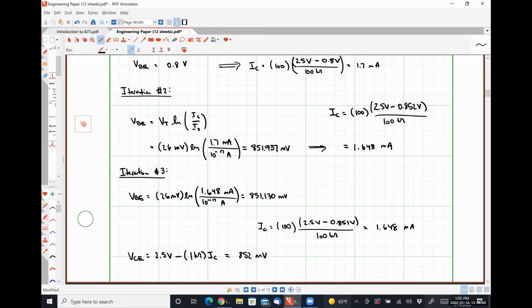So what could we do to push this guy further into the forward active region, right? What if we weren't comfortable with biasing this guy on the very edge of saturation? Now, for a BJT amplifier, being at the edge of saturation really isn't going to mess things up too much, because we know that behavior in the soft saturation regime is effectively almost the same as behavior in the forward active regime anyway. So as long as we didn't have an amplifier that was going to push this guy too far one way or the other, we'd be pretty stable here, right?